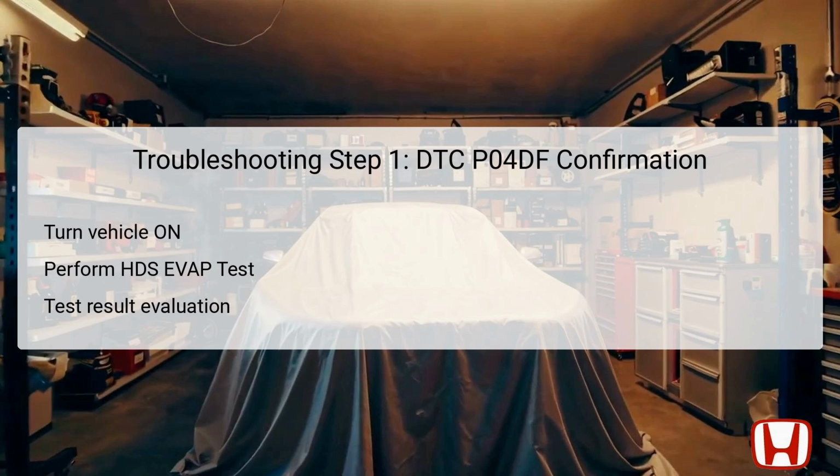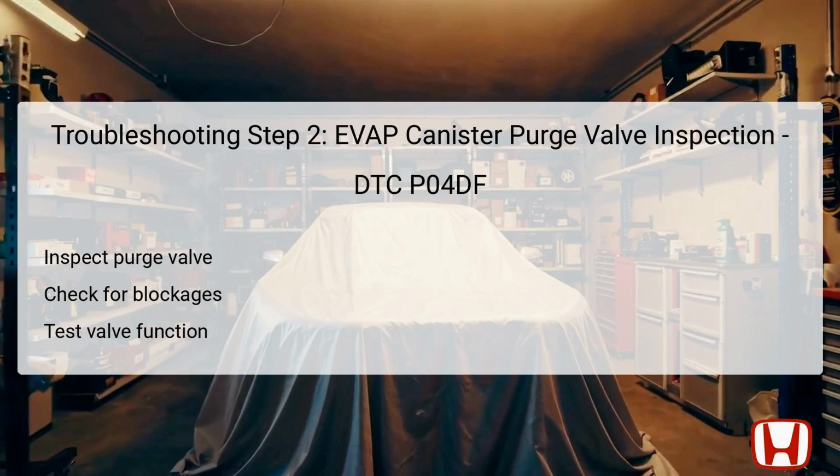If the results show OK, you may look towards other parts of the emission system, or conclude that another issue may cause the symptoms. In the second troubleshooting step, focus on the inspection of the EVAP canister purge valve, an essential component linked to DTC P04DF. Begin by removing the valve while ensuring the connector remains attached. This process will allow for direct access to test the valve's functionality effectively.